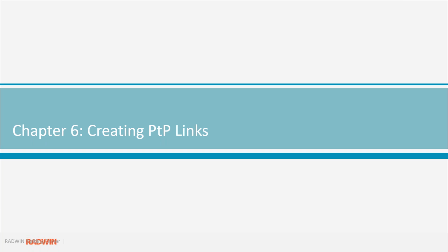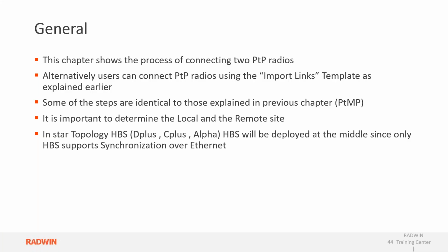And the decision, the most important is the throughput and the antenna gain that you are using. Now, again, like we did yesterday, if there is an obstacle with topological area, you can bypass it with point-to-point and not point-to-multipoint.